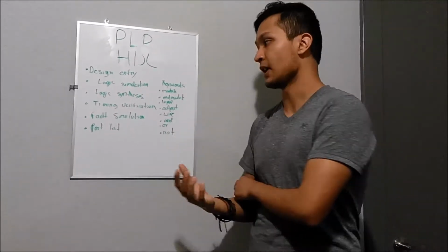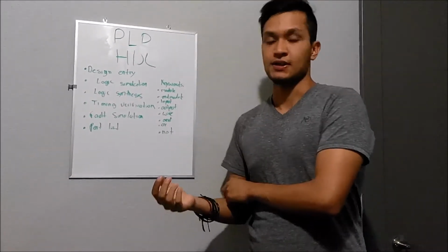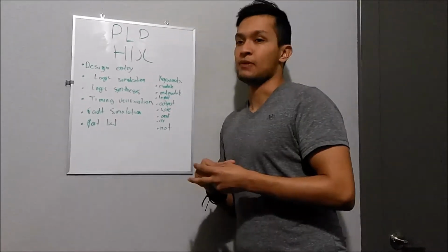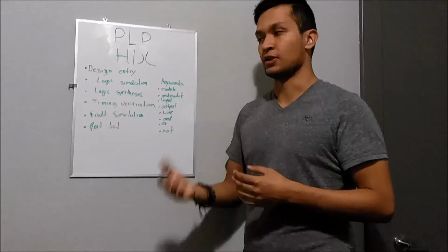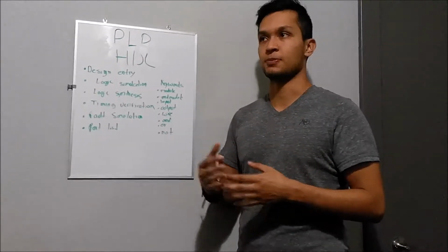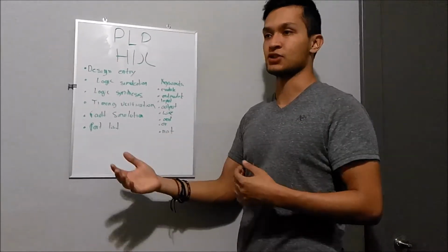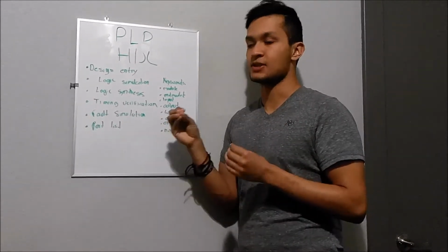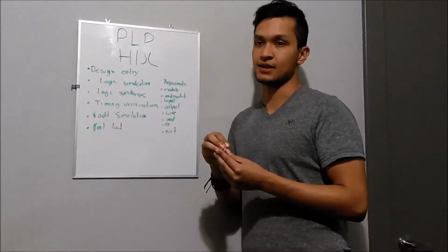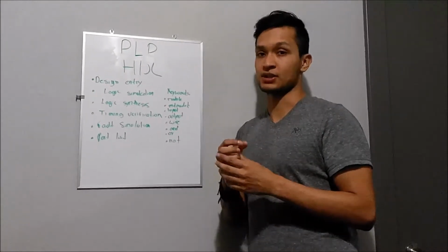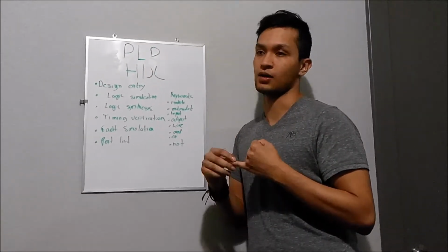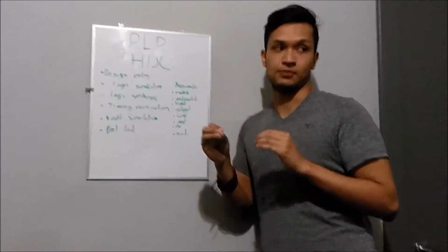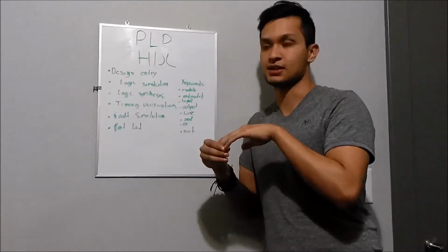And also we can find the fault simulation. This fault simulation allows the program to maybe find the errors after the manufacturing of certain devices. Because these are really, really small devices and specialized tools and processes, maybe a tiny particle can be inside of these circuits.